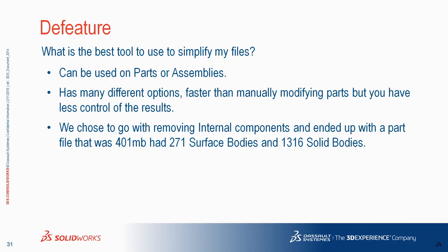All right, so Defeature. This kind of falls into what's the best tools to simplify our assembly files. Defeature can be used on parts or assemblies. It has many different options. It is faster than manually modifying the parts, but you have less control over the results.